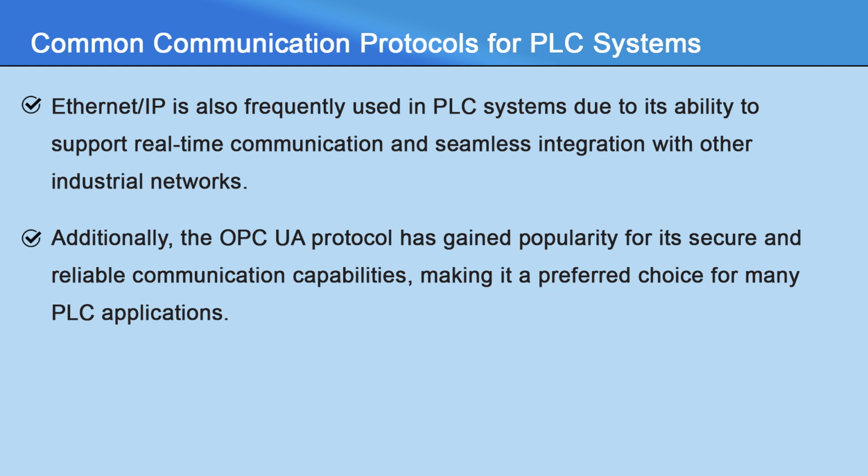Additionally, the OPC UA protocol has gained popularity for its secure and reliable communication capabilities, making it a preferred choice for many PLC applications. Overall, the selection of the communication protocol for a PLC system depends on the specific requirements of the application, including the types of devices you are using, the speed of the communication and also the level of interoperability which is required in the system.